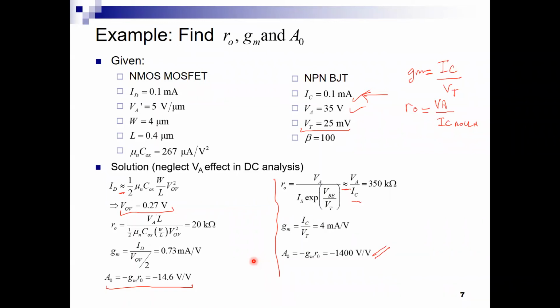What we can do for the MOSFET to increase its gain is really to try to increase its current, and GM is proportional to ID, and we need to increase the size of the device. Okay, there are some nonlinear dependencies here, so I'm not going to discuss them. There are some trade-offs, but they suggest to us that if we increase W and increase L proportionally, sorry, they kept the current constant, I apologize. So if we increase W and increase L,